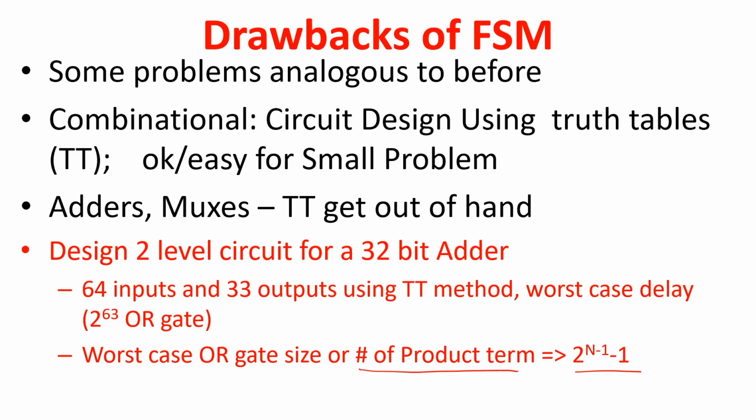This problem is in the combinational circuit domain. Similarly, in the sequential circuit domain we face exactly the same issue. Whenever we want to model a register or a counter of more than 16 or 32 bits, the FSM size gets out of hand. We will not be able to design it by hand, and it is not desirable to do it with a computer either.